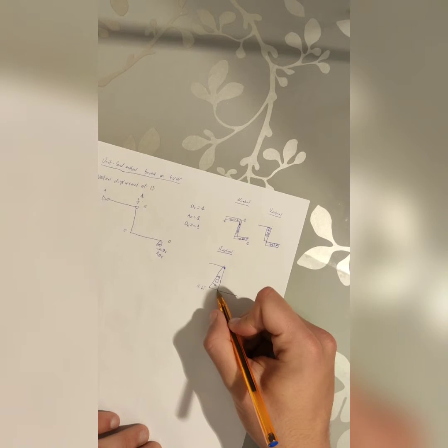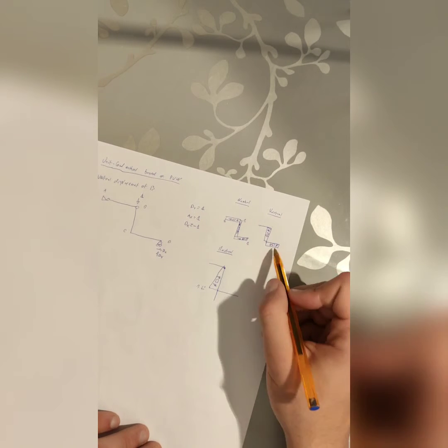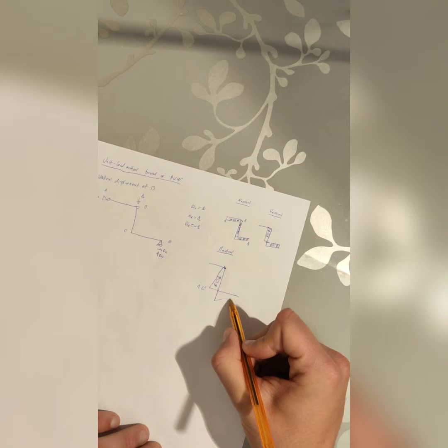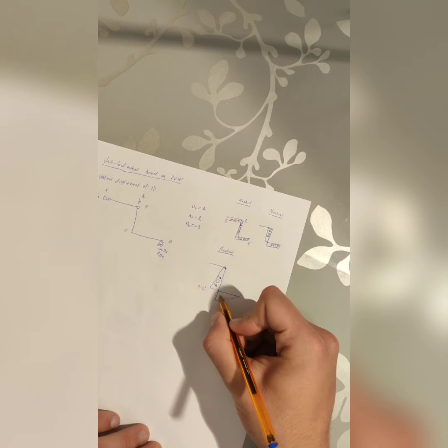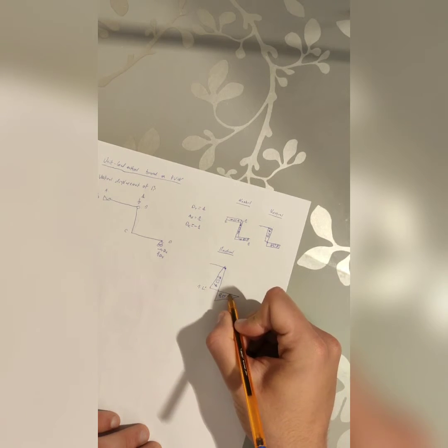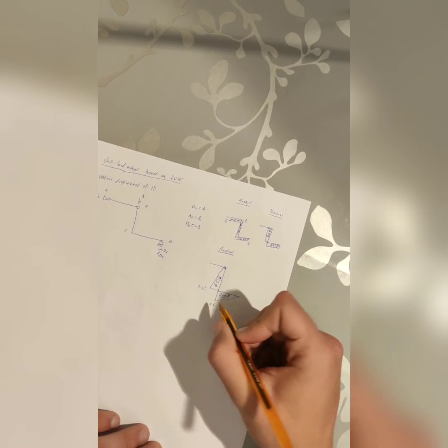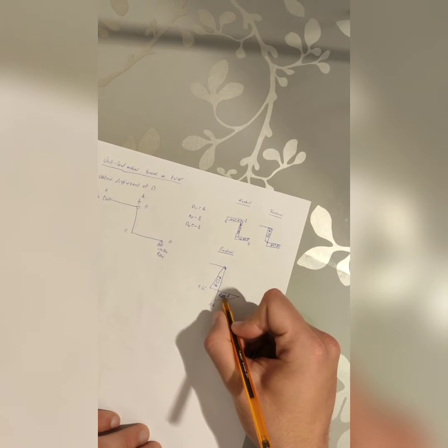Here the moment is conserved, and since it is a free end and the slope is the same, we have once again the same triangle. The value of the height is 1 times L. The fibers that are in tension are below.